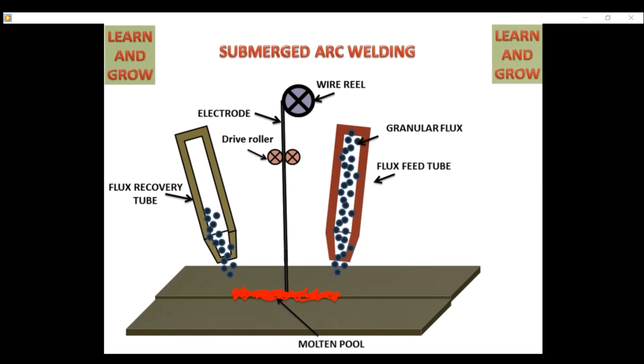So we call it gas metal. The word metal here is not tungsten. If I said gas tungsten, it is non-consumable because tungsten refers to the electrode. But when I say gas metal, you can understand that the electrode is metal. What metal? Compatible with the workpiece material. If I said gas tungsten arc welding, the electrode is made of tungsten, and it is a non-consumable electrode.